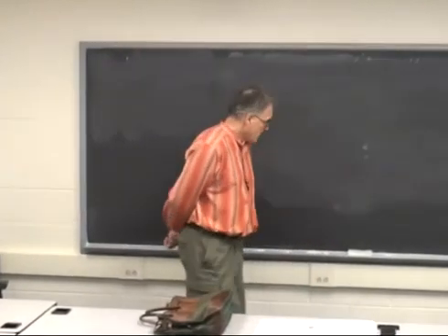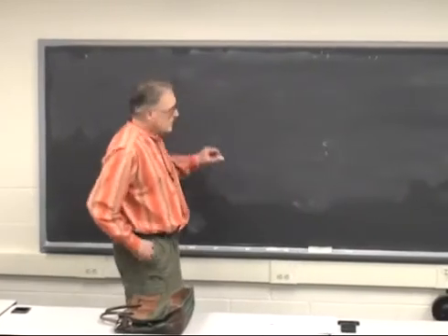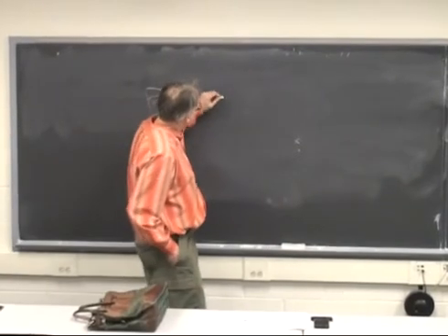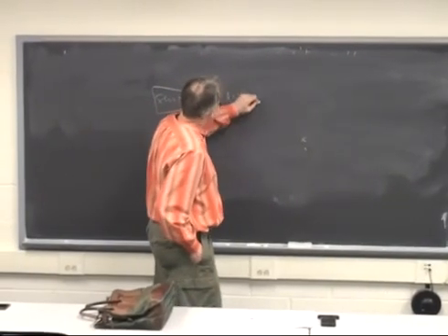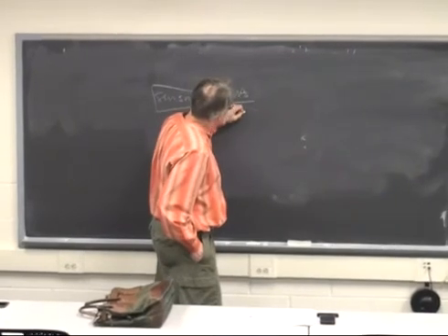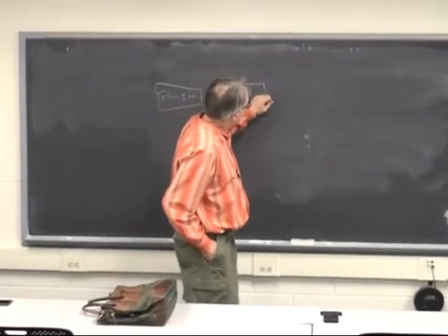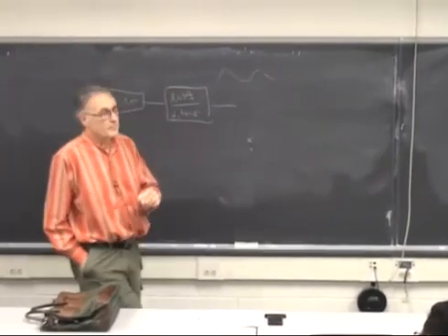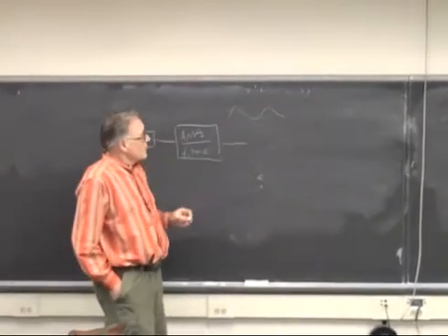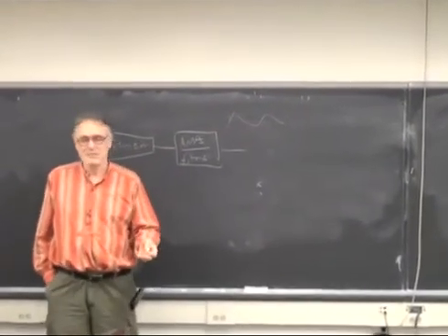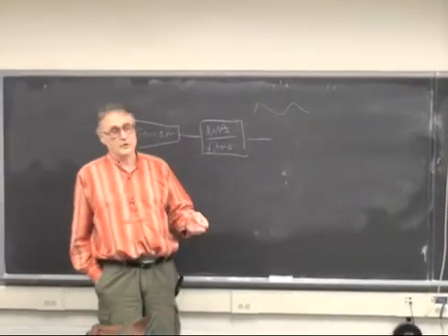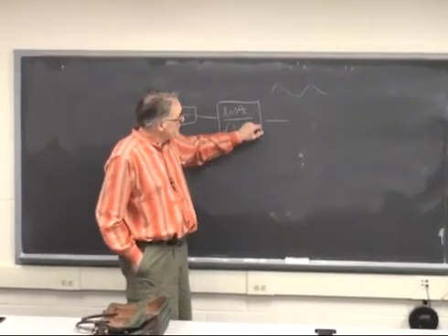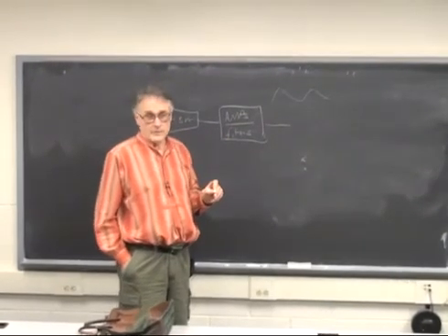I think that the basic circuit I gave was a sensor and then a combination of amps and filters. So what comes out of here now is an analog signal which is proportional to the opacity of your finger. Wouldn't it be nice to, and of course the main point of this lab is to do the next steps in software to threshold it or to fast Fourier transform it, but you could also imagine extending the circuit to do some of these functions automatically.